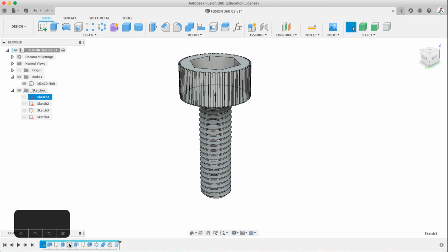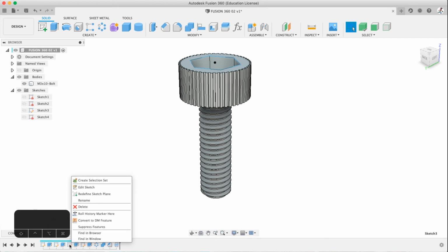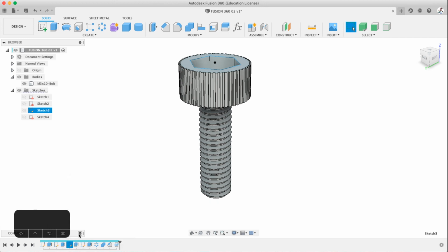It's thinking harder, it's working harder, and things might not work properly, but it's still workable. If the icon here turns red, the blue turns red, then that reference has disappeared. It's gone. And Fusion is saying, oh, what's going on? I don't have any reference here. I don't know what you're talking about anymore. And everything that's associated with it will not work properly, especially if you have joints and moving objects and other things that are attached to it as a reference. So please make sure you are keeping the same objects. You can always change them. Just don't delete them if the referencing objects are really important. If you can re-reference it, and that's a future video, but just be wary of that.